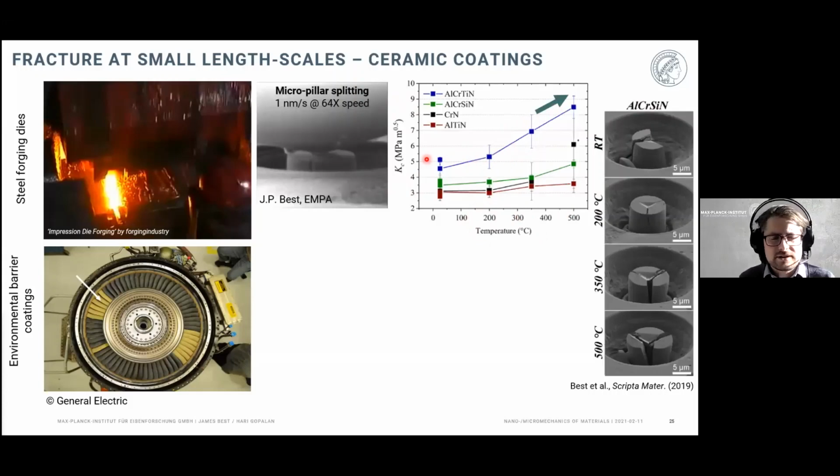And so now I think you've developed a little bit of an understanding that we can dissipate energy through plasticity, so dislocation movement through a material, and that these barriers for dislocation movement are also thermally activated. So if we increase the temperature, then we make it easier to move dislocations along those slip systems. And so in effect, that's what we see here, that at increased temperatures, we're able to get more and more dislocation plasticity through the material. And this leads to a toughening type approach.